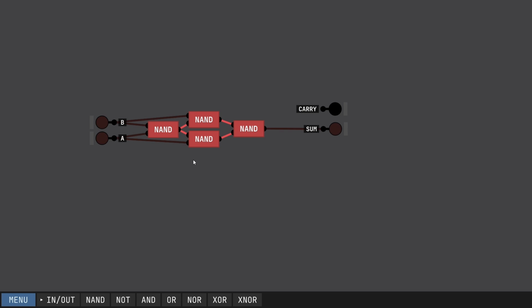And this is going to give us our sum. So, see? But this also has this NAND gate in the middle right here. And this is just a reverse AND gate. So if we put a NOT gate right here, just to invert the signal to make it into a normal AND gate, we get an adder right here. See? And it gives us the exact same logic as the other gate, except now we're saving a transistor pretty much, so it's a little more optimized. So this uses 8 transistors right here, this XOR gate, and then this uses 1 transistor to make the NOT gate. So in total this is 9 instead of 10.